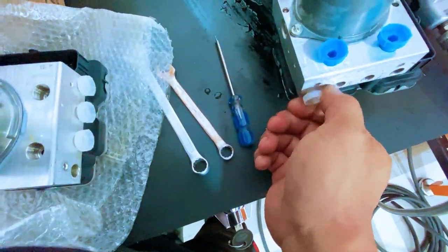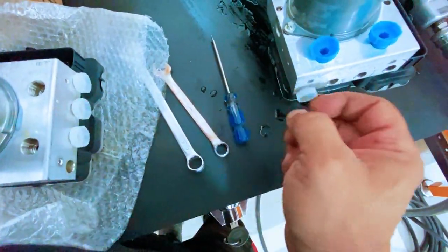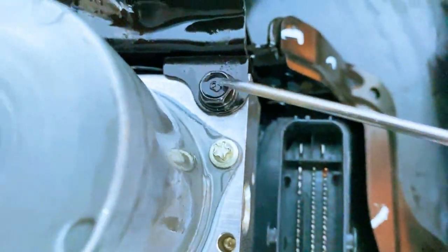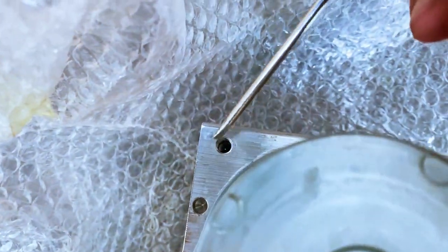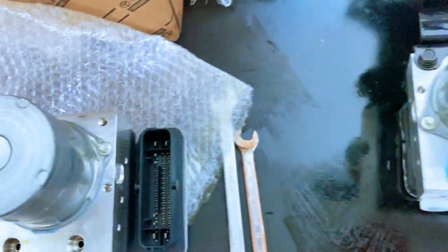Toyota's diagnostic flow is very clear. First, confirm the symptom. Then identify the DTC. Then identify the suspected circuit or component. And only after that should we perform the detailed circuit or component inspection. This prevents unnecessary parts replacement.